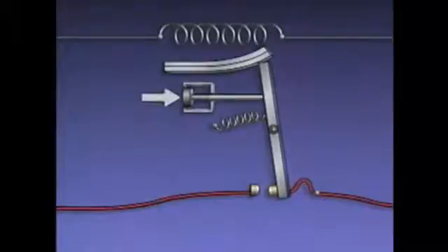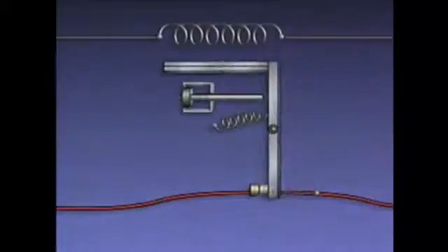When the reset button is pushed, the mechanical linkage is moved against the force of the spring so that the linkage is snapped back into its original position. The bimetallic strip once again holds the linkage in place. The linkage holds the overload device's contacts in place, which makes it possible to restart the motor by supplying current to the M-coil.